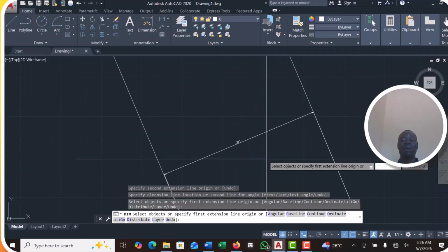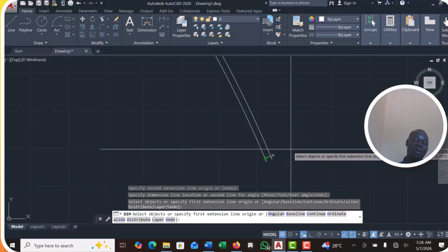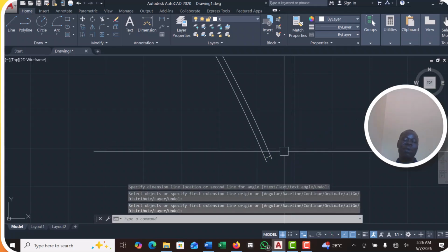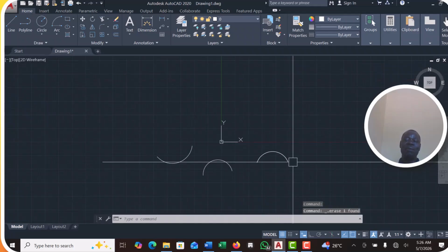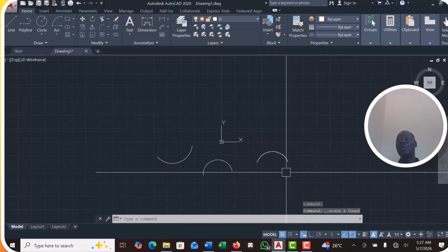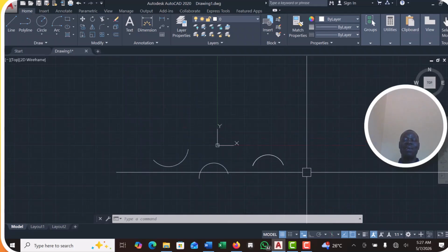200 millimeter. So sometimes you need to zoom in order to see certain things. And this one also confuses learners. They offset and they think it is not there. So now when it is like this, you may think you have not offset, when you have already offset. This is really there. So the zoom command is very, very important.